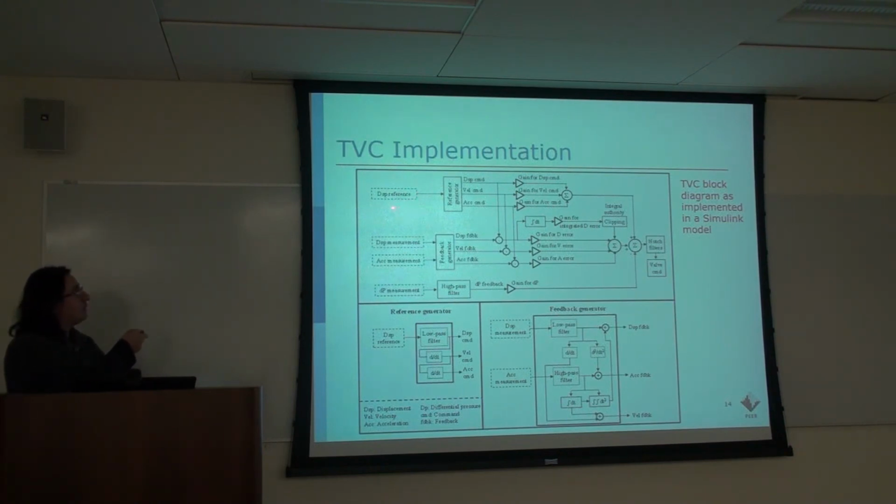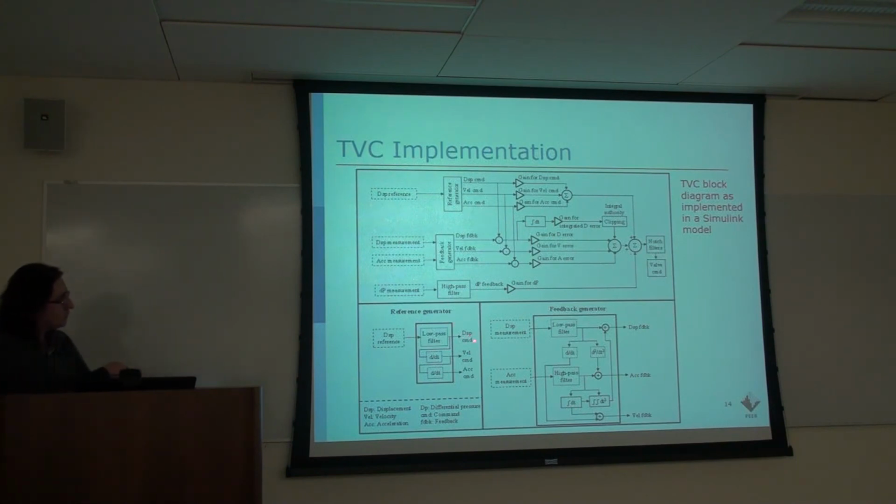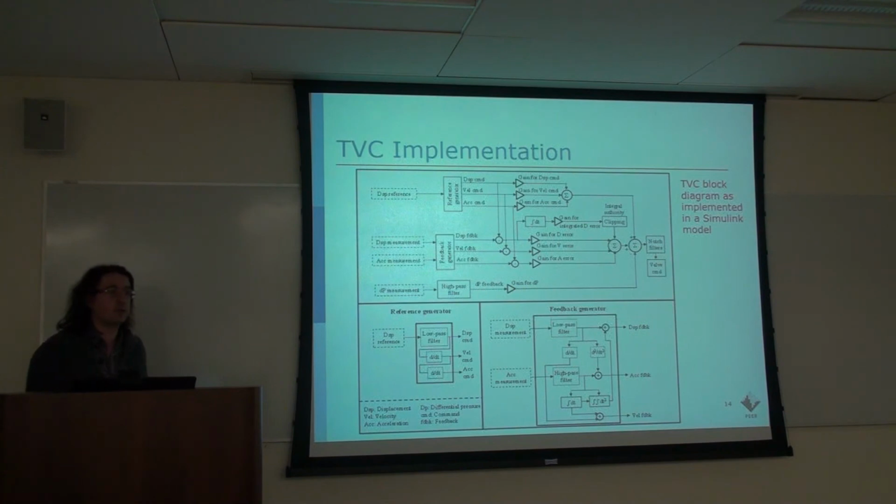Let's say in hybrid simulation we have the displacement command, computed displacement, and then from this we compute the displacement command as directly equal to the computed displacement, and get the derivative of this to get the velocity command, and do a second derivative to get the acceleration command.